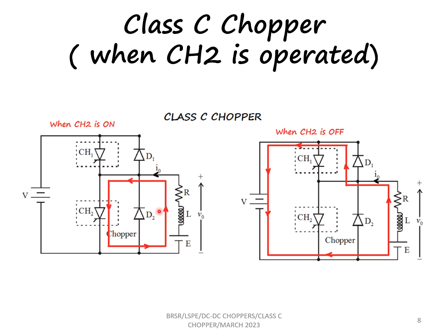Now when this chopper 2 is switched off, the current flow will be from the load through the diode D1 back to the source. So the current flow here is from the load to the source. In the earlier case, it was from the source to the load. So the average output current can be either positive or negative based on the chopper's operation.